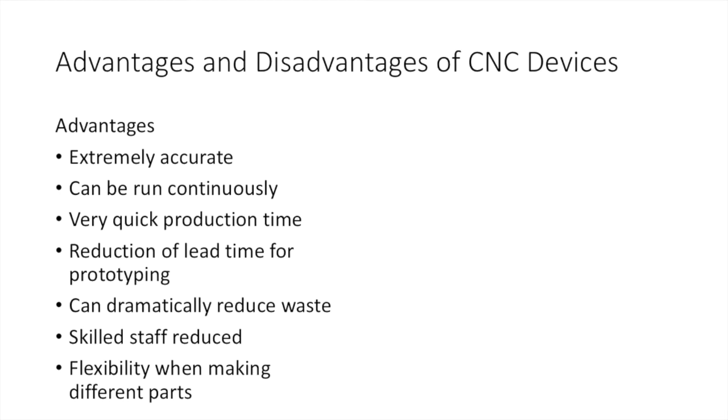And there's plenty of flexibility when you want to manufacture different parts. If you've got the 3D printer, again to use an example, it'll print a different part every time you want to print something. You don't have to just repeat the same process. If you're using an injection molder, for example, instead, then you'd have to have a new mold every time you want to create a different part. Well, using a 3D printer, it generates it from scratch without the need of a mold. So your big costing with regards to tooling, for example, like mold pieces and things like that, is gone. You haven't got that problem.